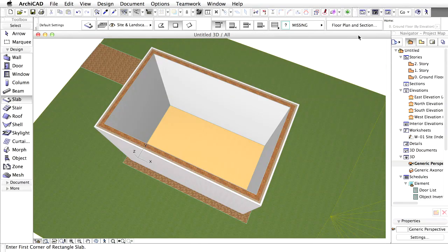Instead of setting all the parameters for the newly created elements all the time, you can also save and reuse parameters by defining favorites. Similar to attributes, later on, you can export and import the favorite settings between projects. You can apply the favorite settings to existing elements as well, and use them as a basis for new elements. You can access the favorites using the Favorites palette.